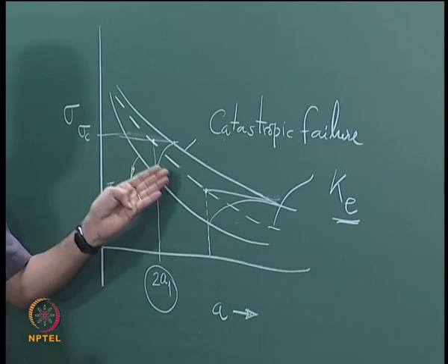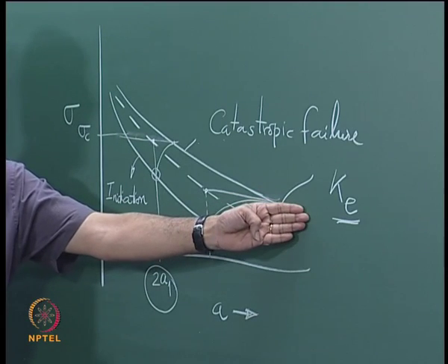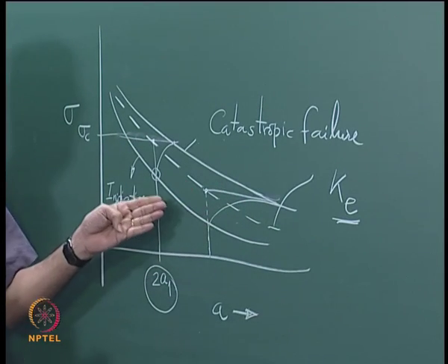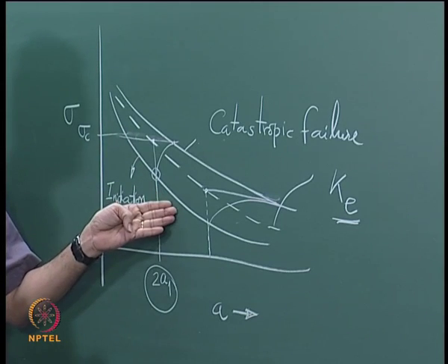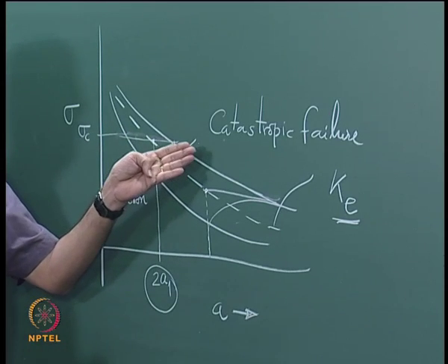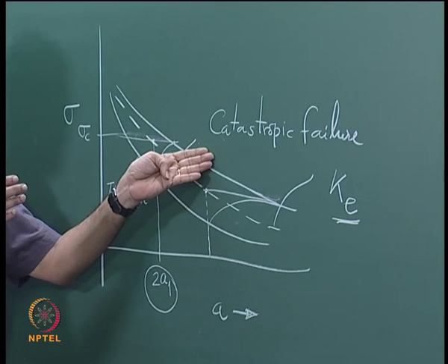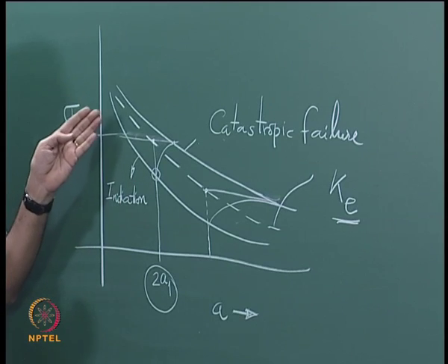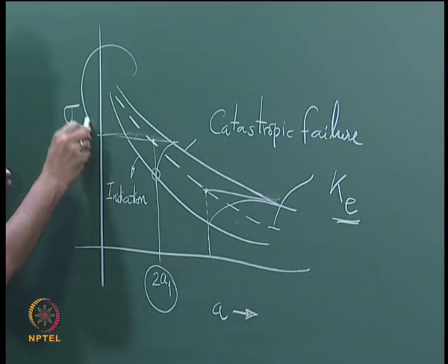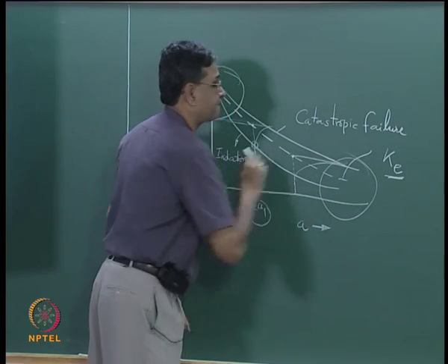Whatever the discussion that we are going to do later, you could construct it based on the apparent toughness, or you would also find graphs giving initiation toughness, apparent toughness, and the toughness at which catastrophic failure occurs. All the three graphs people do it. Now, the idea is we want to find out how do we handle data in these two zones.